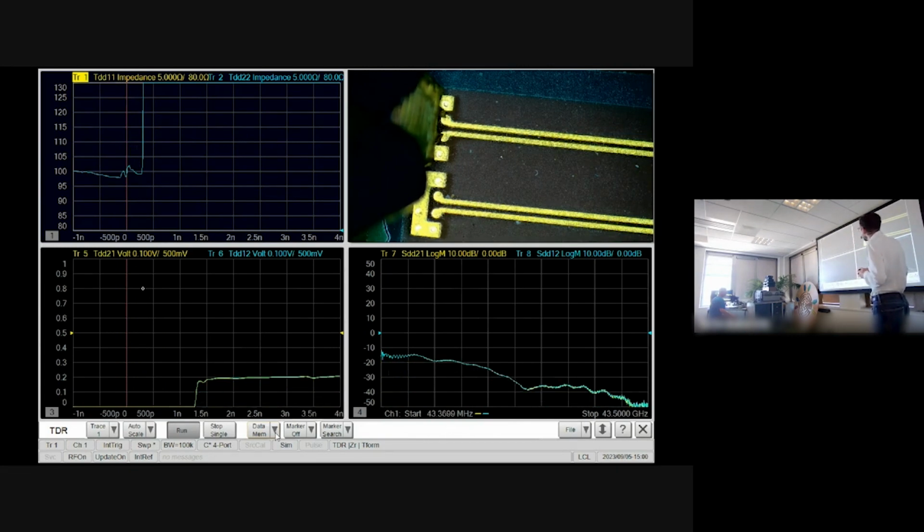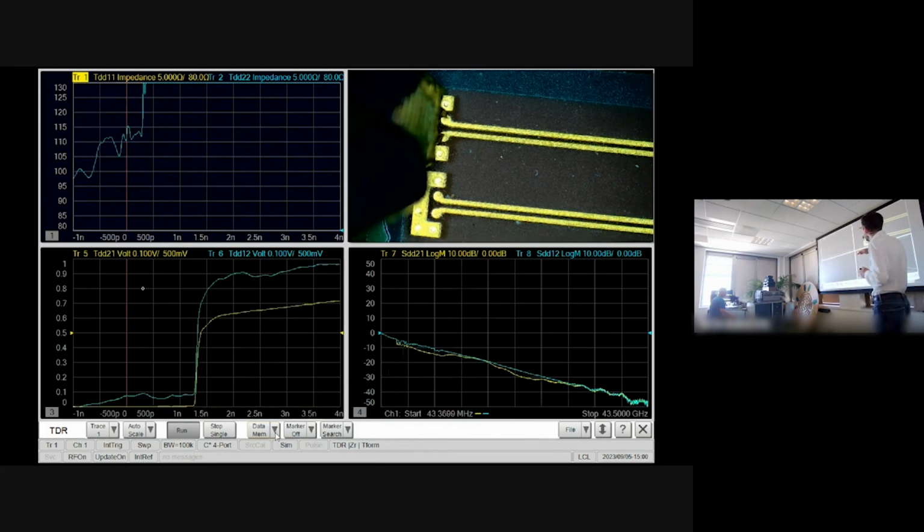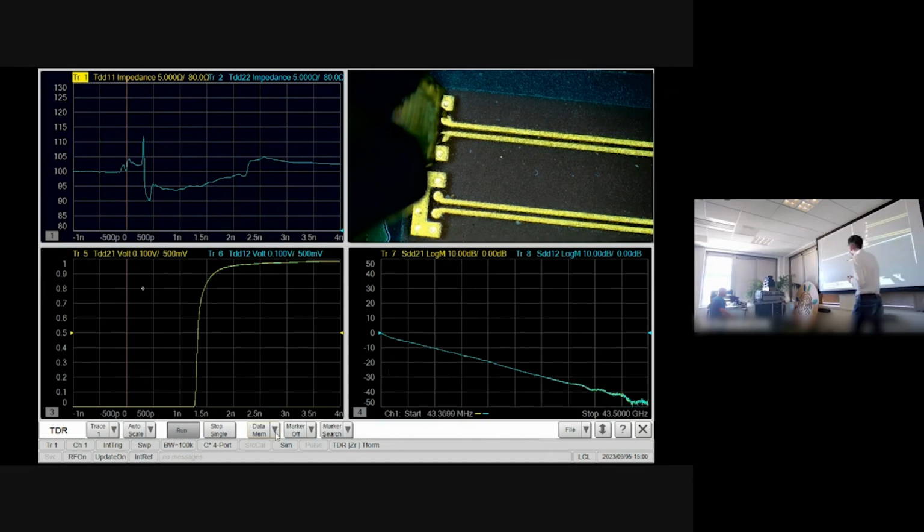So you see we're starting to touch down. And now we see this strange transition region, and then something which ramps up slowly from 95 to about 100 ohms. Okay, maybe correct, something that we try to design. Why do we have this slope? Because in layout it's perfectly the same along the length. I don't know, but maybe if you have some experience with TDR, you know that slopes can be indicative of loss. So nothing very surprising yet.